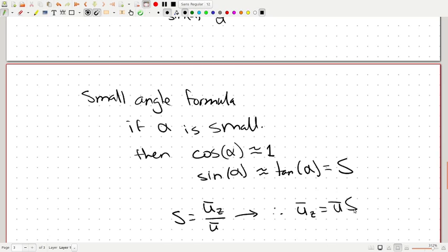If we think about this, just to do a quick sanity check, this makes sense because if there's a certain velocity going down channel and the channel slope is small, then much of that velocity is going to be in the horizontal, but some of it will be in the vertical. A typical, let's say, gravel bed river slope is something like 1%, so 1 part in every 100 of that river's velocity will be bringing that water vertically downwards. Okay, great. That makes a lot of sense.